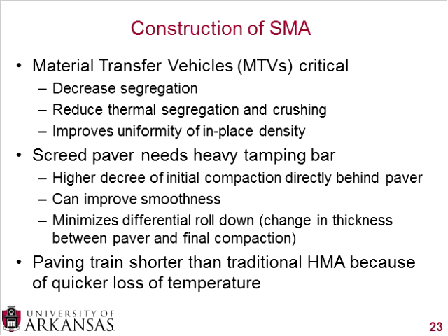It may have some segregation, either thermal or aggregate. It allows it to remix it. So by taking this material, putting it in a material transfer vehicle, and remixing it, you can decrease the aggregate segregation, and you can reduce thermal segregation and any sort of crushing that you may have.